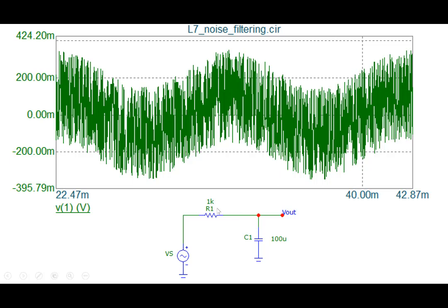And the reason why we are able to do it with a capacitive circuit is, all of you may recall, we'll just see today, that the voltage across a capacitance cannot change instantaneously. Which means that the voltage across the capacitor will have difficulty following the rapidly varying part here, right? And the slowly varying part, the capacitor is able to follow. So that's the principle behind filtering. The fast variations in voltage that you apply here, the capacitor is not able to follow, while the slower variations, the capacitor is able to follow.